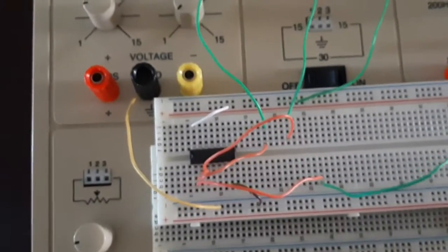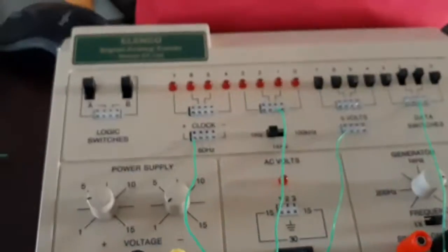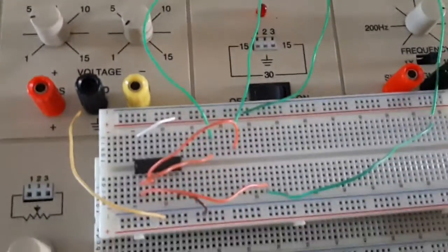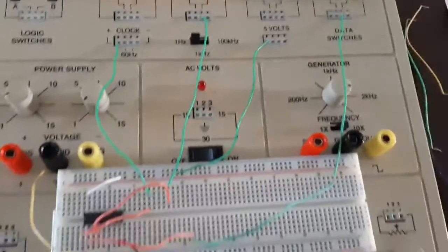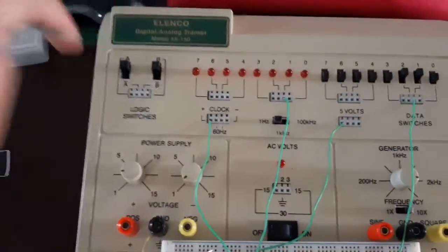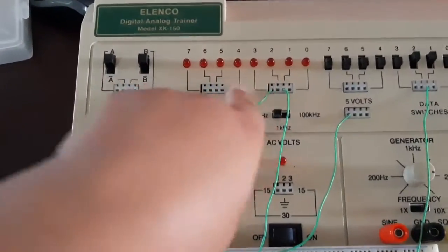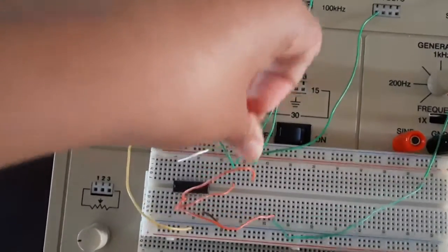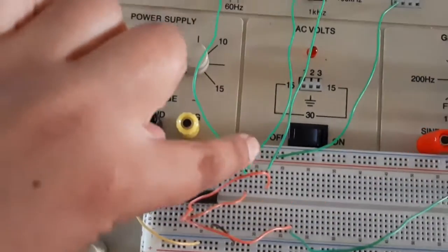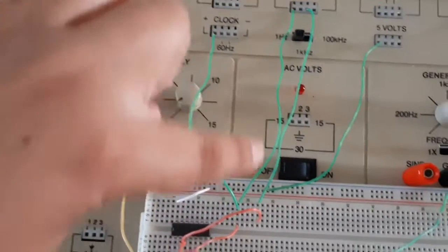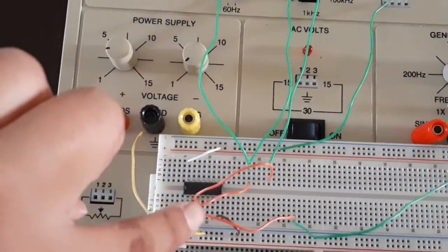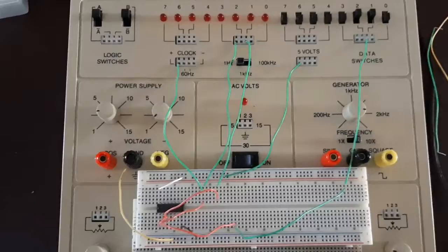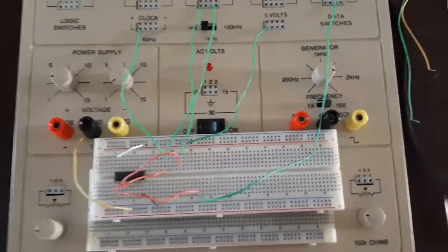Another thing we have to do is show the 1 hertz clock signal on an LED, which I'm going to do right now. I'm going to connect to LED number 3 just to have a little bit of distance there, and bridge it in the same row where I have the 1 Hz signal. So now that row, besides the clock signal connecting to pin number 2 and becoming input B, is also connected to LED number 3. And that is how the circuit is built.